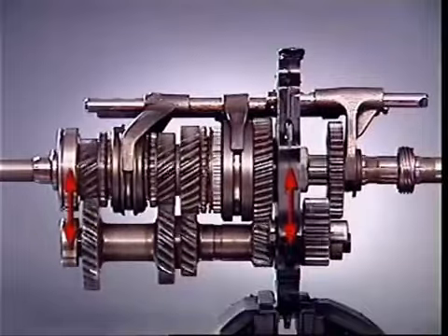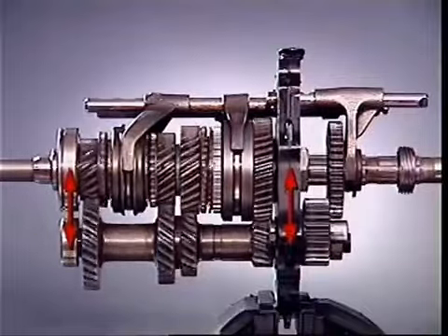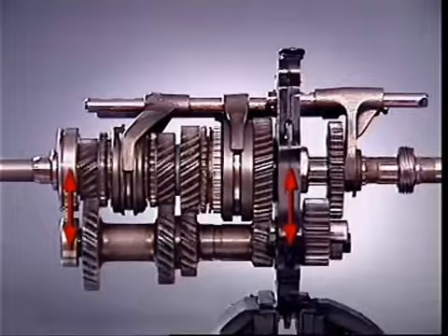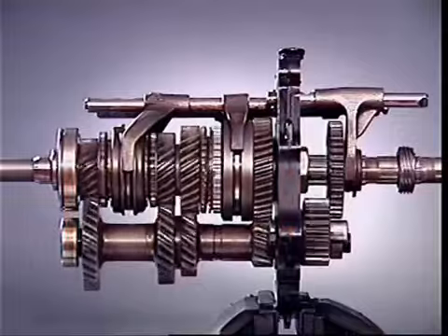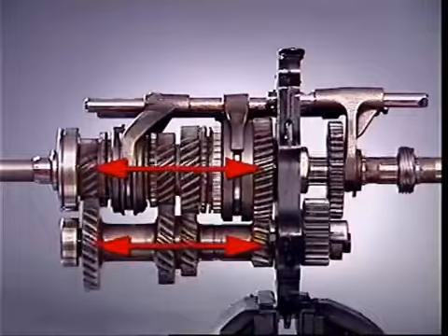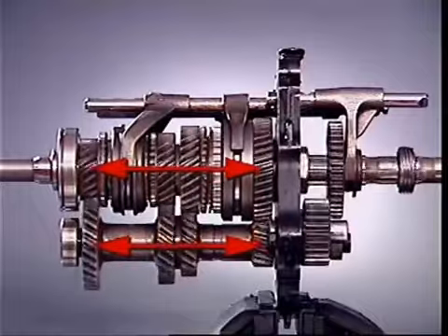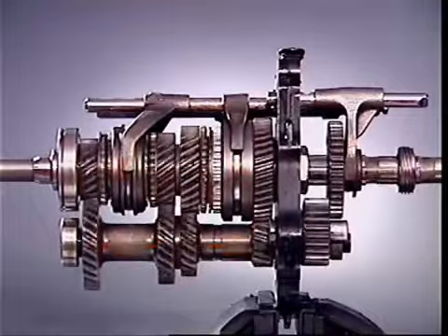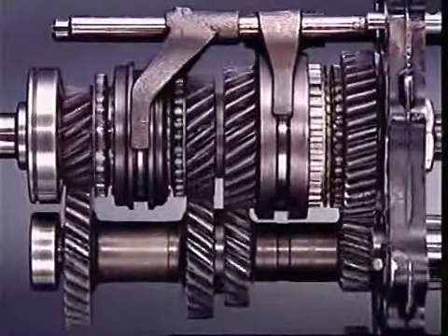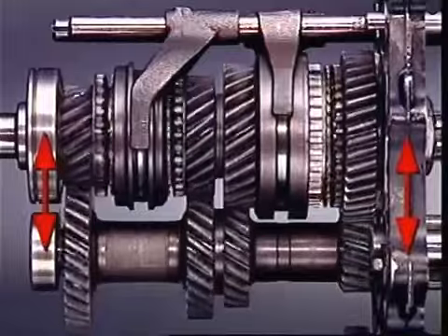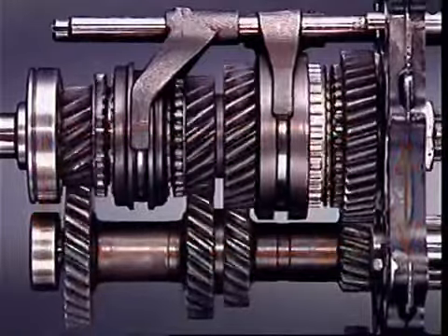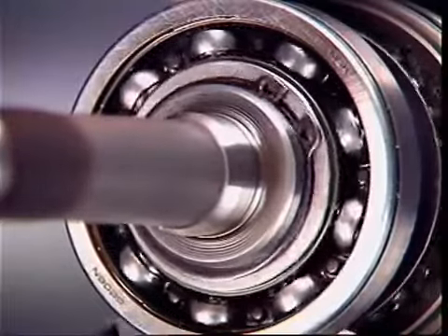Radial loads try to force the gears and shafts apart. The bearing therefore carries the load along its radius. Thrust loads are applied along the length of the components, so the bearing must cater for side thrusts. In many cases, these loads are combined, and some bearings designed for radial loads will also accept light thrust loads. This applies to most ball bearings.